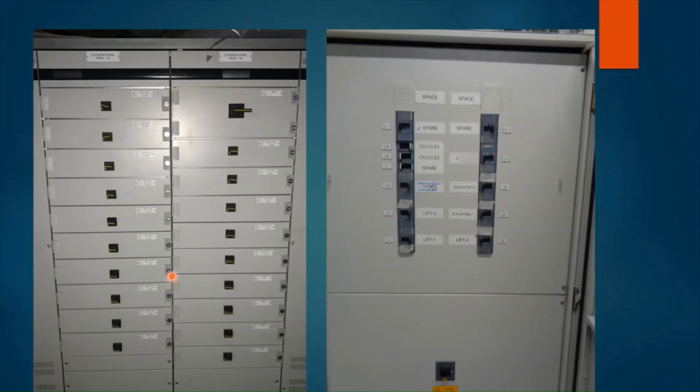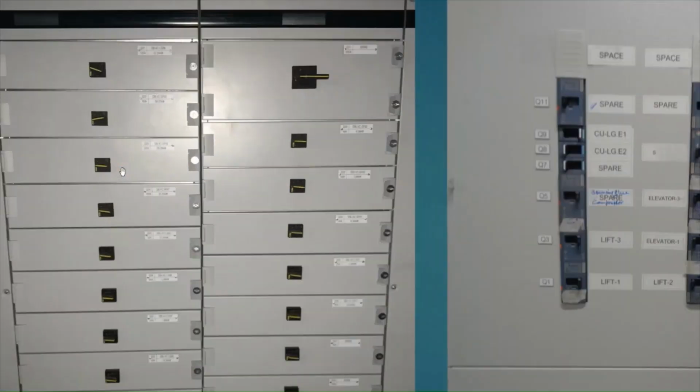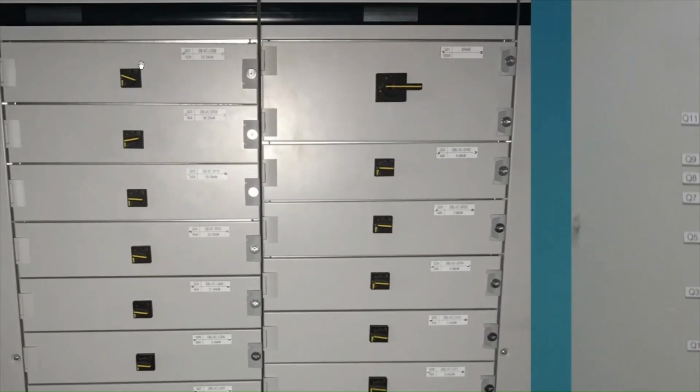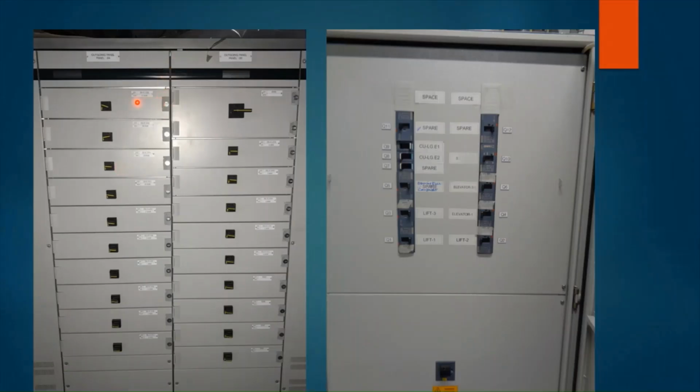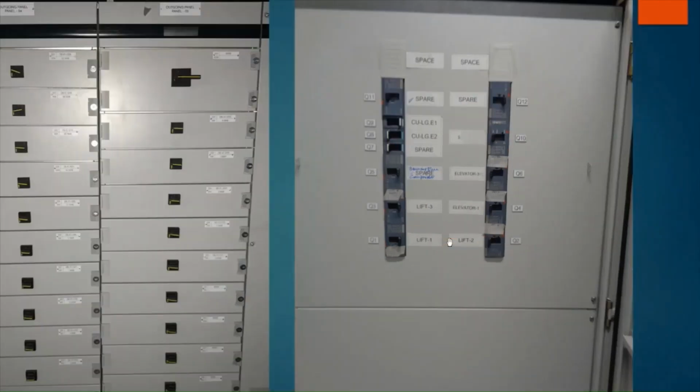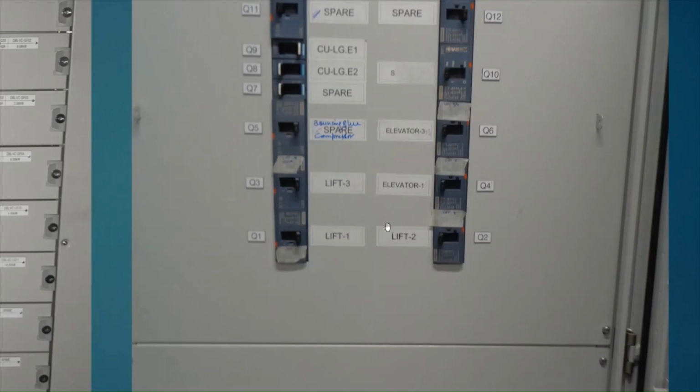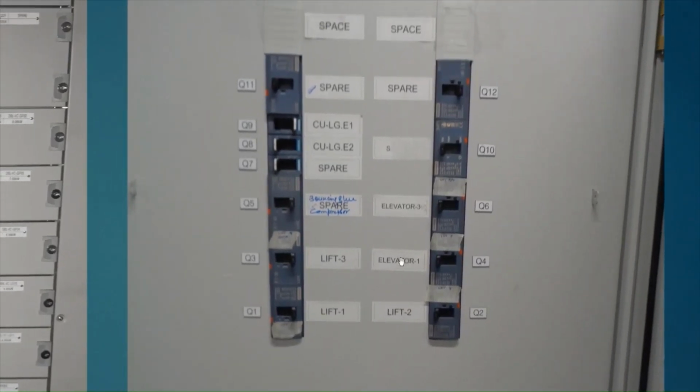Now, these are 2 real photos of molded case circuit breakers. The first photo shows a molded case circuit breaker installed at a main distribution panel. And of course, a molded case circuit breaker does not look like this. This is just a lock or a rotary handle. It's just an accessory for a molded case circuit breaker. If we open this door, inside we will find the known shape of a molded case circuit breaker. The other photo shows a sub-main distribution panel which feeds and protects different loads that include lifts. Each of these lifts is protected by a molded case circuit breaker.